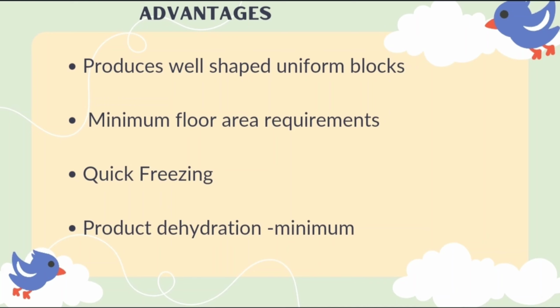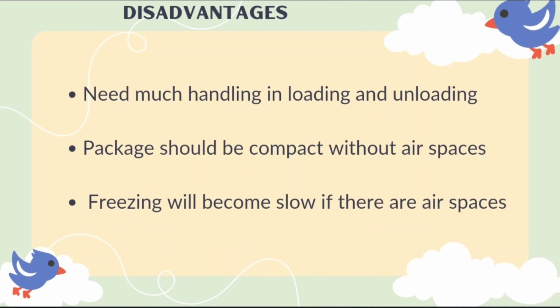The advantages of horizontal plate freezer are: first, it produces well-shaped uniform blocks; second, minimum floor area requirements; third, quick freezing; and fourth, product dehydration is minimum. The disadvantages of horizontal plate freezer are it needs much handling in loading and unloading. Second, the package should be compact without air spaces. Freezing will become slow if there are air spaces.